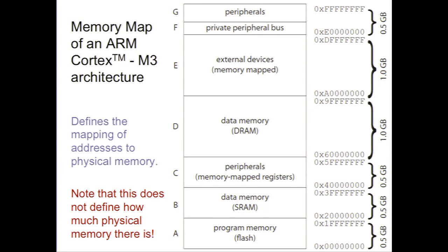Question about refreshing dynamic memory: does the controller have any idea which parts of the memory need to be refreshed, versus parts that are not actually being used and hence don't need to be refreshed? I don't think so. The controller that does the refresh is built into the hardware of the RAM chip. I don't think it has any visibility into what the operating system is doing. Memory allocation is typically handled by the operating system, so it's going to just refresh everything.